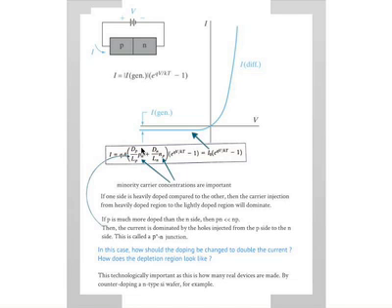What that's saying is that if Pn is much larger than Np, which means that the N-type material is much more heavily doped, then you can ignore one of these terms. Obviously, there will be much more injection from one side than the other, so one of these two components dominates. If P is much more doped than the N side, then Pn is much less than Np, and the current is dominated by the holes injected from the P side to the N side. This is also called a P plus N junction. This is very common in real devices, and it simplifies the equations quite a bit.